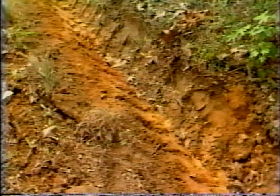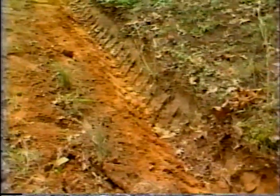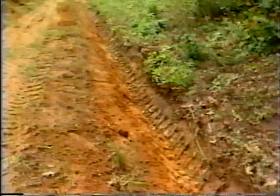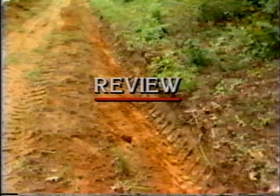Ditch maintenance with a motor grader results in a V-shaped ditch with a well-groomed back slope and foreslope. The ditch is cleaned out to the original flow line and has a smooth flow line so that water will move freely down the ditch. Now, let us review the steps followed in this operation.